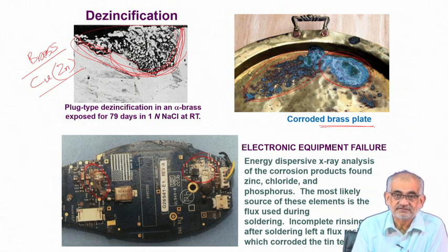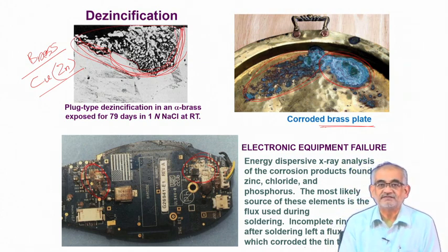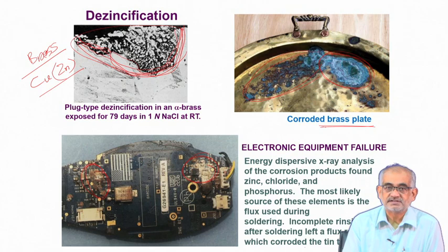That means we are using a filler metal, and the filler metal causes localized fusion or melting of the metallic parts between two different sides, and compositionally they are very close but not exactly the same. So typically you can use lead tin solder. These days lead tin solder is not used anymore. So you may have, let's say, indium tin or indium gallium tin or some other forms of low melting